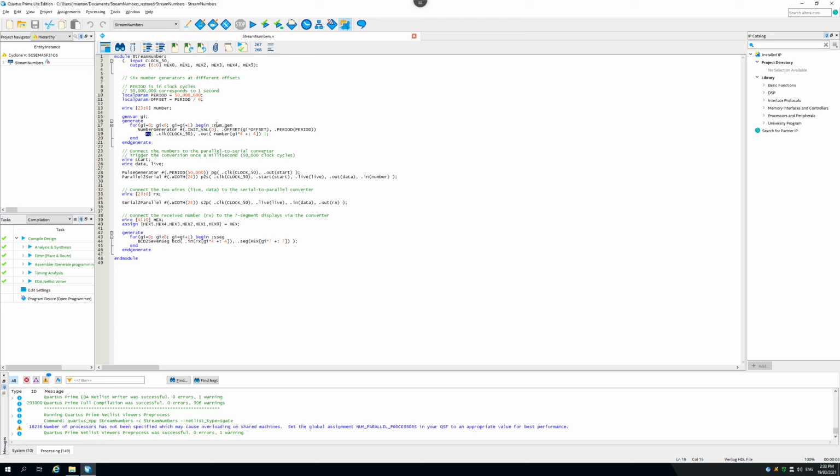But by naming my block, the name of each chip is going to be numgen 0, 1, 2, 3, 4, 5, 6 .ng. So by naming the block, I end up with a unique name for each of these chips I'm making. Every chip has the same surname, ng, but its first name is numgen 0 or numgen 1 or numgen 2, etc., where you add the generated variable to the end of this name. And that's why you need a genvar up here, because it's special, it gets added to names.